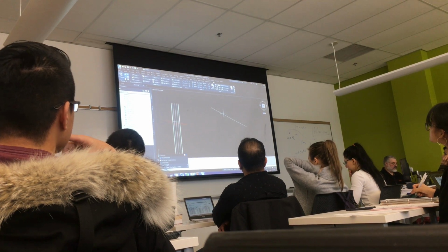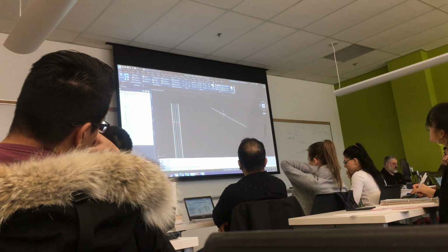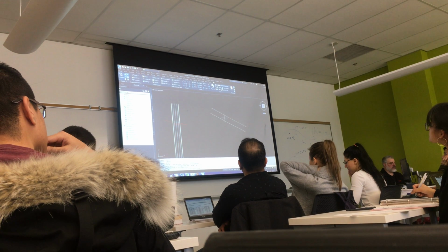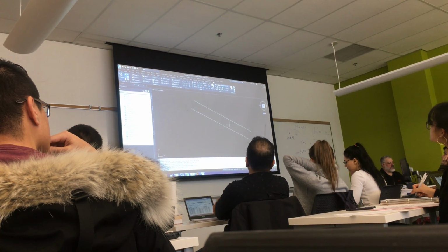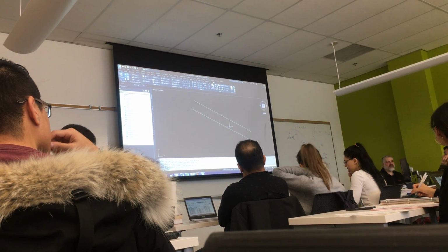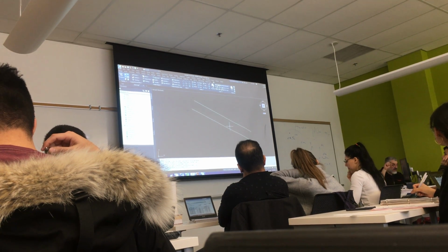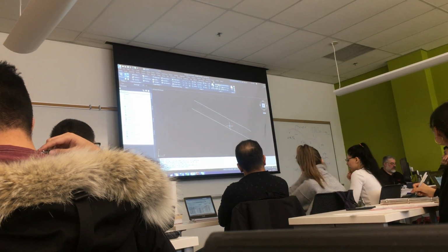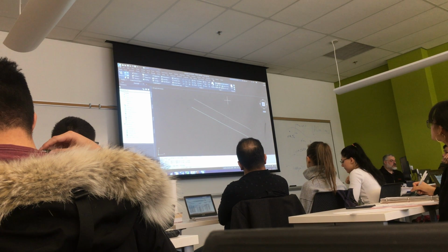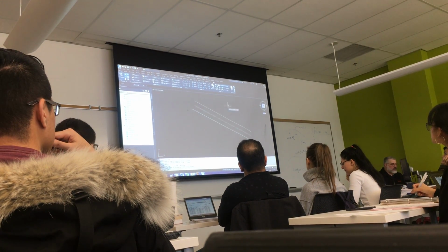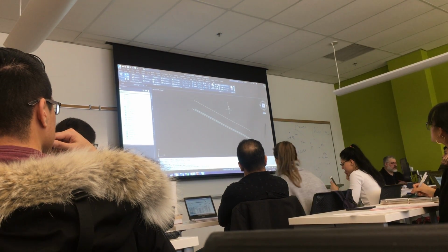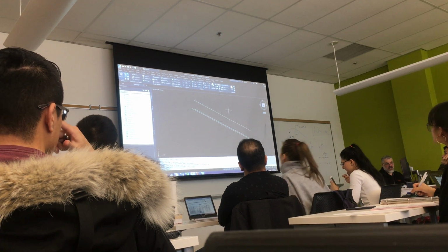Offset 10 meters. So I'm going to offset this by 10 meters. There it is. Okay? Now, that's 10 meters. That's not what we mean by depth. Okay? The thickness or the depth of the material is vertical. I'm going to make a copy of this straight down. Turn your ortho on and go straight down 10 meters. Different solution. Everybody see that?